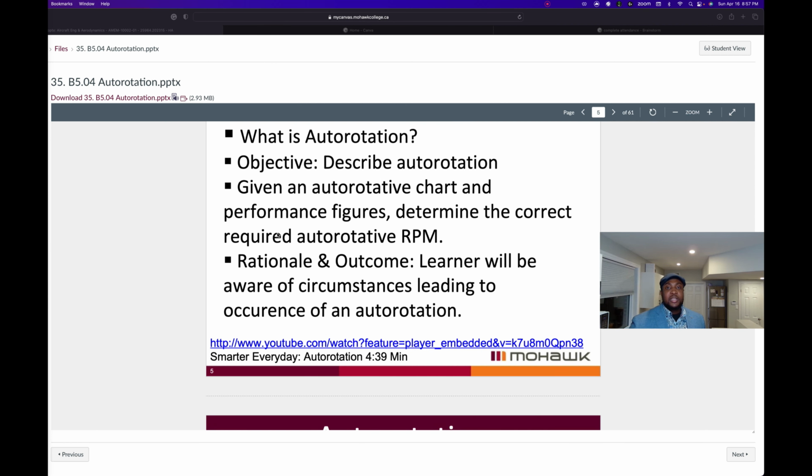During auto rotation, a high inertia rotor system freewheeling at a proper RPM will store large amounts of kinetic energy throughout the descent. What that means is there's a high amount of energy, and it's likely that after you go through your phases of first disengage, push the collective down, aviate the helicopter, flare, correct, touchdown, you're likely to have sufficient energy in the system to get a soft, nice landing.